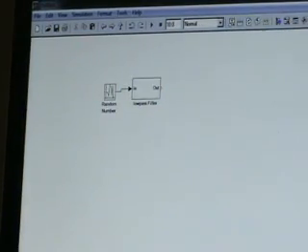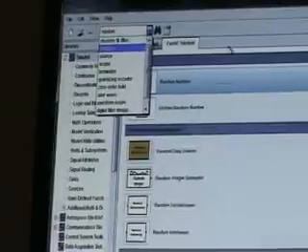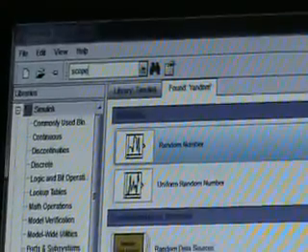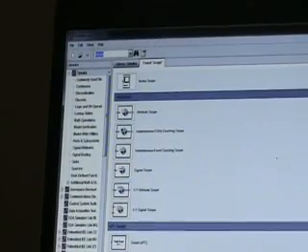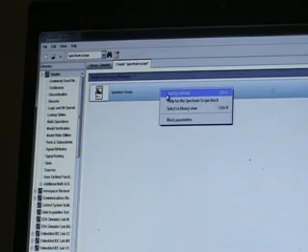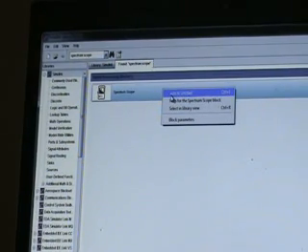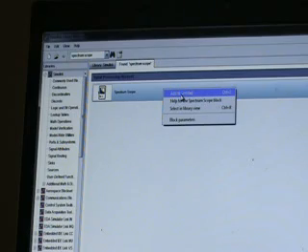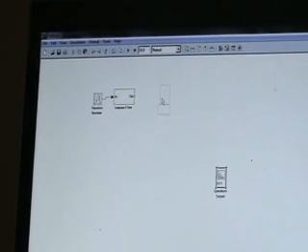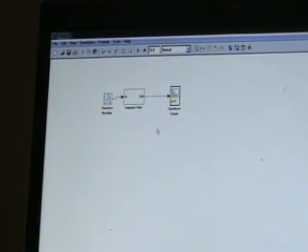Now again we need to have an output. We normally see the output in Simulink using a scope. Here, as we need to see the frequency output, we take the spectrum scope. This is the spectrum scope. As we are seeing whether it's attenuated above some frequency and below some frequency, we need to take the spectrum scope. We add this, and we give this as the output of the filter.